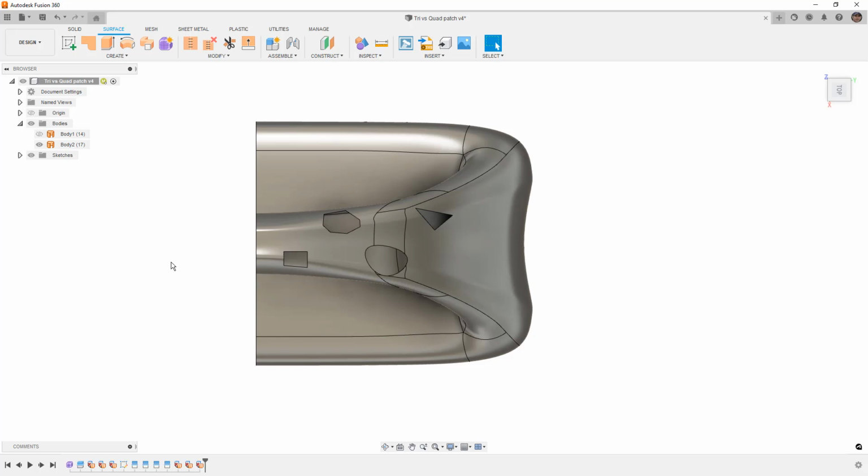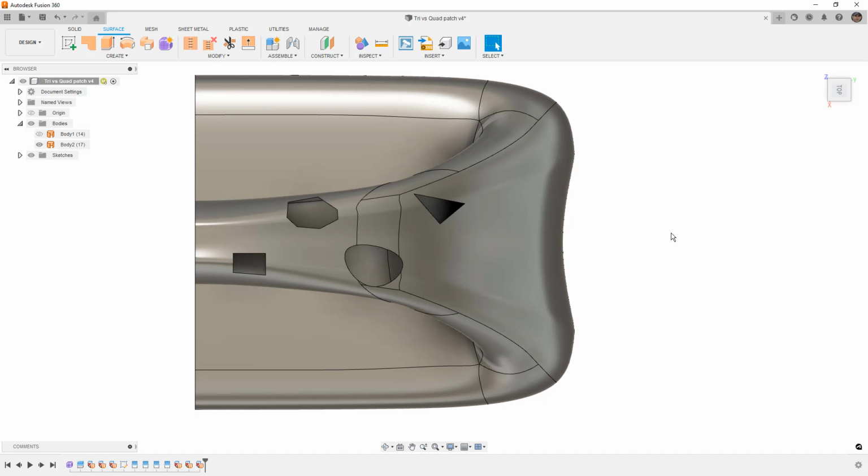Now, it might be because a section of the surface is bad. The geometry is not great. Or maybe you added some additional details and you need to sort of fix certain areas. So what we want to do is we want to take a look at the couple of cases that I have highlighted here. We've got a nice rectangular four-sided opening. We've got one with multiple sides. We've got one that was created with a spline that has curvature continuity all the way around. And we have a triangle.